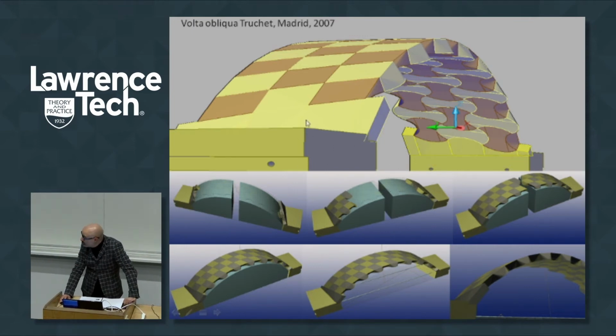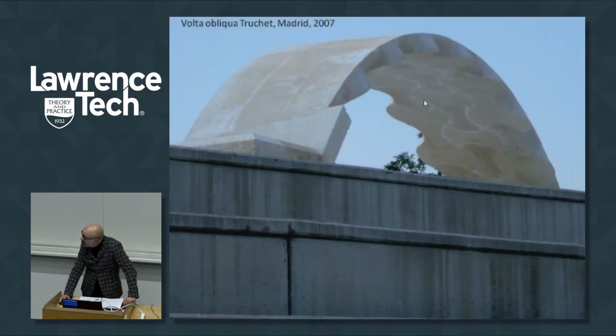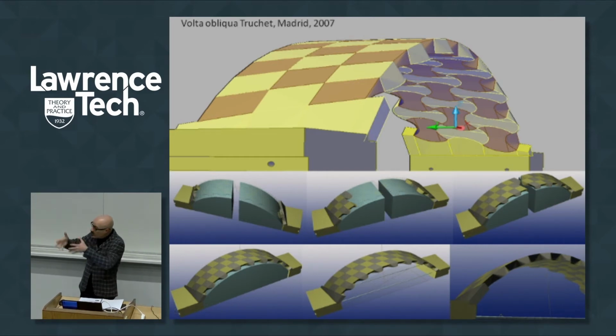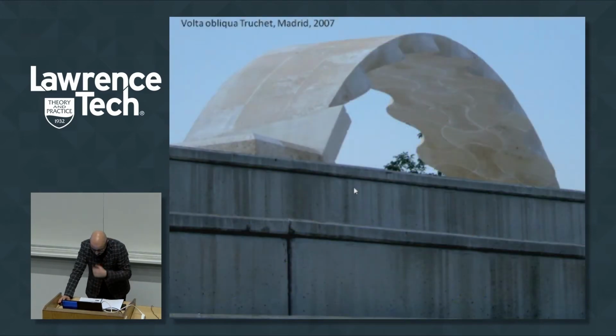And so you can see the deformation at the base of this structure using this kind of ashlar conformation. You can imagine that just to assemble this kind of vault, it's not possible to use the canonical, traditional formwork, but we invented two different formworks that move horizontally just to create the anchoring, because it's not possible to put the last keystone from a vertical position.